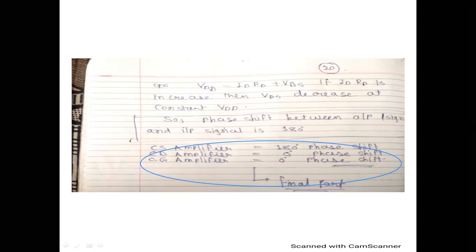Now see, this is the example of JFET. N-channel JFET has IDSS equal to 8 milliampere, sorry, and Vp equal to minus 5 volt, meaning pinch-off voltage, and VGS equal to minus 2 volt. So it is the basic equation of JFET: ID = IDSS(1 - VGS/Vp)^2, so 8 times ((5 - 2)/5) whole square, 3 by 5 whole square. So answer is 2.88 milliampere. So it is the final answer related to example number 1.